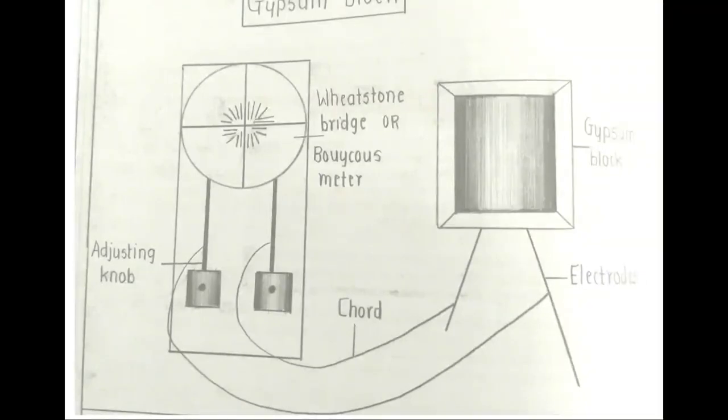Okay. So resistance is measured in ohms. When the soil has more moisture, we can say field capacity. Field capacity means the soil has more moisture. So at field capacity, the resistance recorded is 400 to 600 ohms.